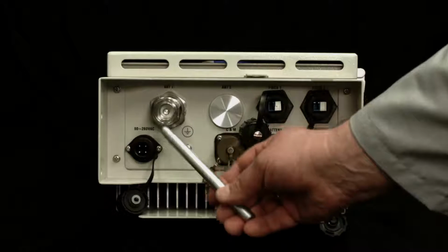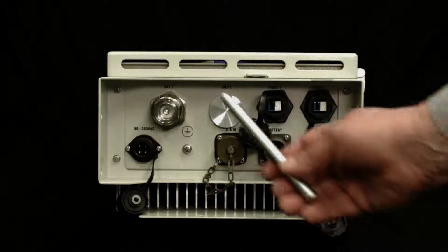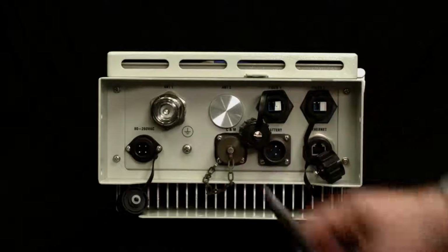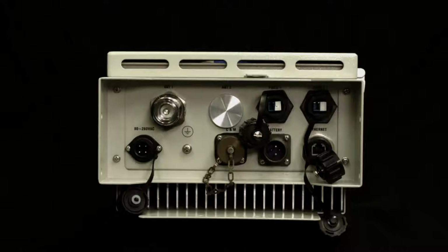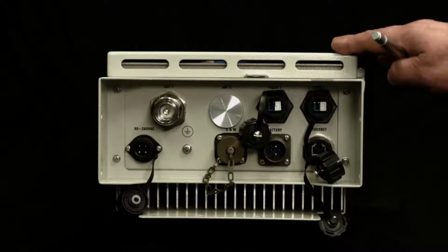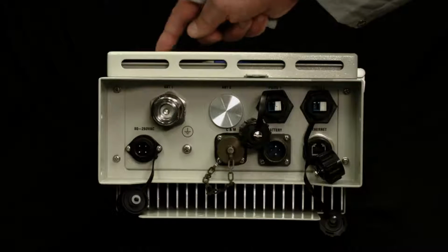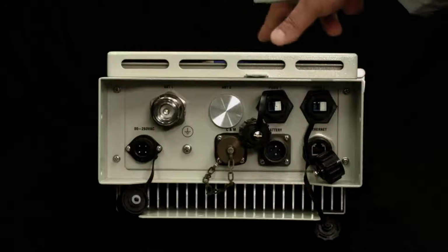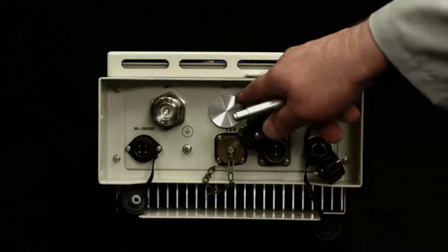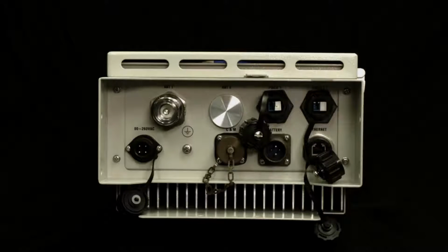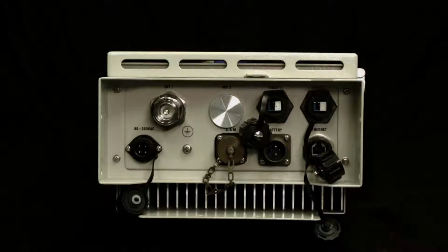Finally, RF interface connector or RF antenna connector. This is DIN 7/16 type RF connector, and the unit can have one or two of them. This is a dual band unit. In a case of having a multiplexer that combines two bands, we have a single connector. But in some cases, based on actual venue, we can have separate antenna ports for each band.